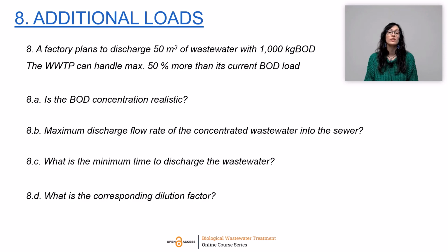First, we have to determine if the BOD concentration is realistic or not, and then we have to make some calculations associated to the discharge that will include the maximum discharge flow rate, the minimum time needed for the discharge, and the dilution factor.